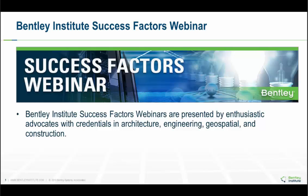Now, in the question there was a mention of a nonlinear analysis. If we're talking about, say, geometric nonlinearities or member property nonlinearities, a nonlinear finite element analysis, at that point I wouldn't be relying on B1 and B2 factors. If I'm using a much more advanced nonlinear type of analysis, then I wouldn't be relying on B1 and B2 factors for that.